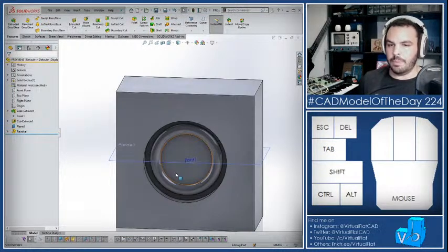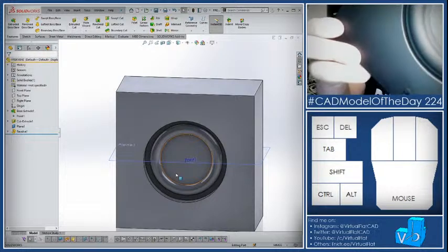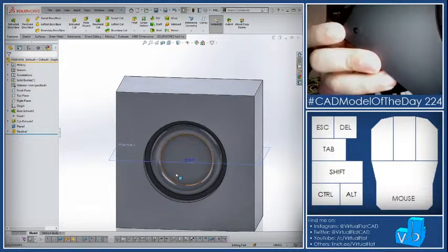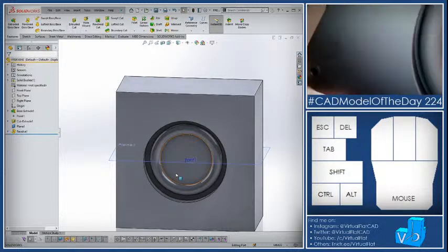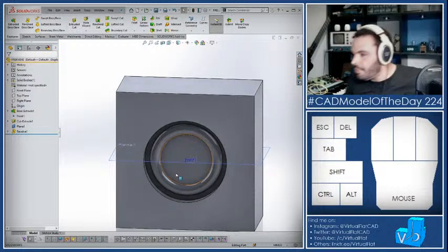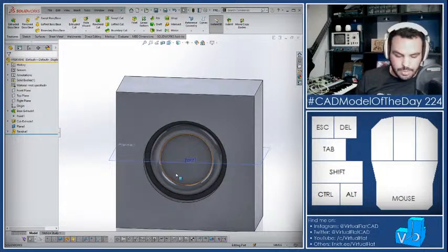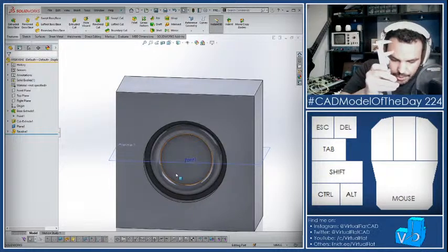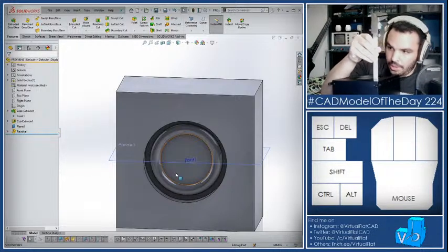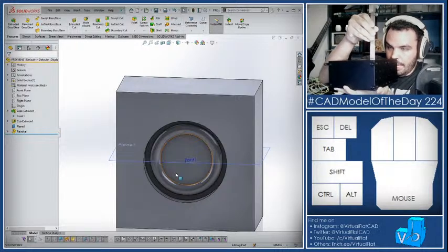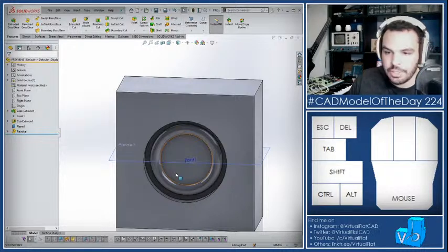I guess on that same face, there are the little nubby, well, the little holes that the little grippy things go into. So I guess I'll tackle those next. A little bit down. Yeah, those things. So I can just take the depth of the hole with my caliper. Really nice thing about calipers, if you don't have a depth gauge, you can just stick the end into it like that and have your own de facto depth gauge.